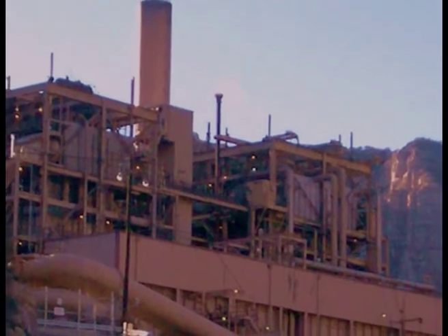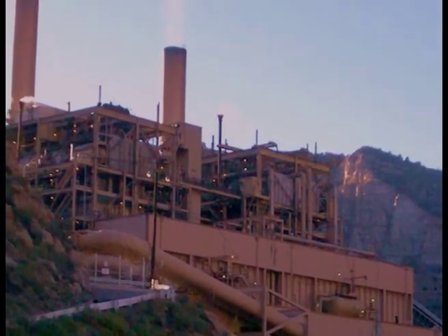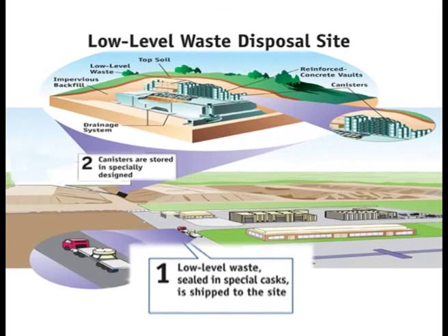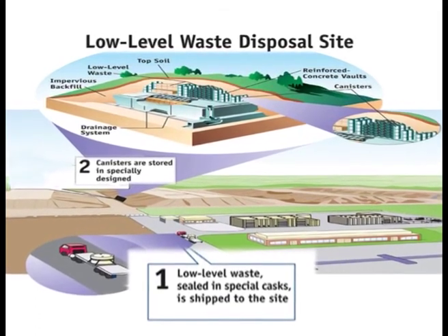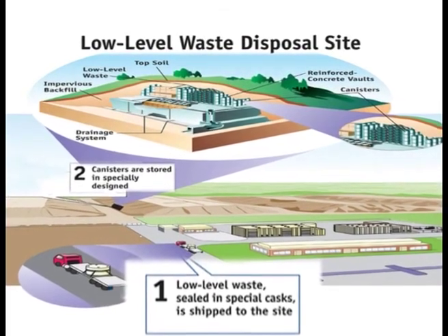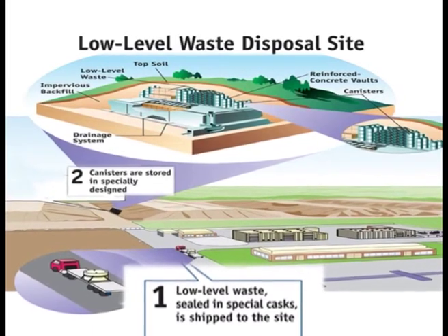Low-level waste, that is LLW, is generated from hospitals and industry as well as the nuclear fuel cycle. It comprises paper, rags, tools, clothing, filters, etc., which contain small amounts of mostly short-lived radioactivity. It does not require shielding during handling and transport and is suitable for shallow land burial. To reduce its volume, it is often compacted or incinerated before disposal. It comprises some 90% of the volume but only 1% of the radioactivity of all radioactive waste.